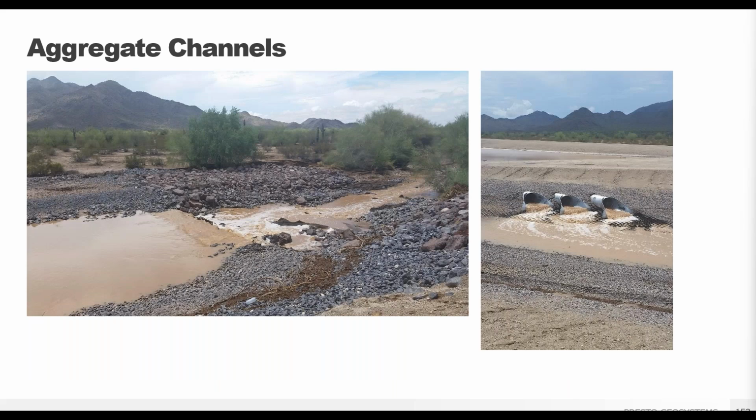And here's the installation under typical flow conditions. And you see the technique tip of adding drop structures, and several were designed throughout the channel to reduce velocity before reaching the end of the channel, so the water will be transported to the groundwater system. With the aggregate protection system, there's little to no maintenance required, and since the aggregate is confined, it won't need to be replaced. The channel is large enough to accommodate large storms without overtopping.